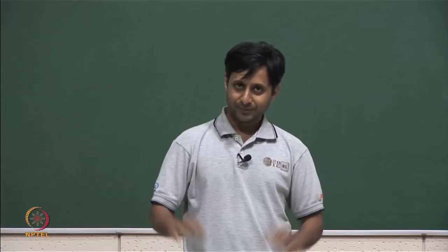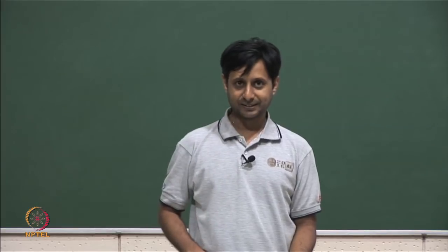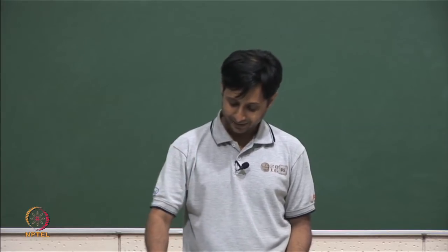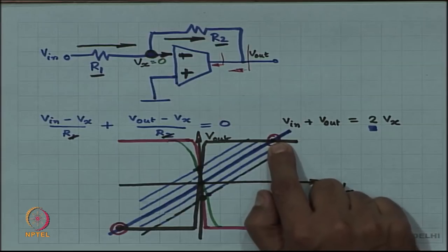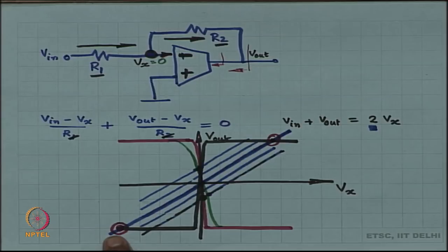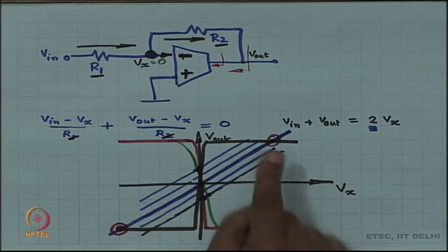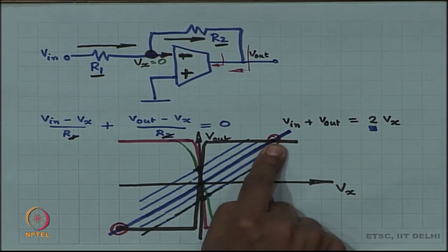All right. So, when you make such a circuit, if you happen to interchange the plus and minus terminals, the circuit is going to remain at either the positive supply voltage or the other supply voltage, right, and it is never going to move from there. Notice the gain, the DC operating point gain, the small signal gain at this point of operation is 0.